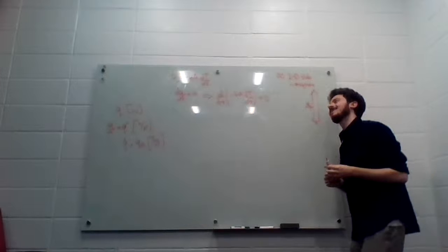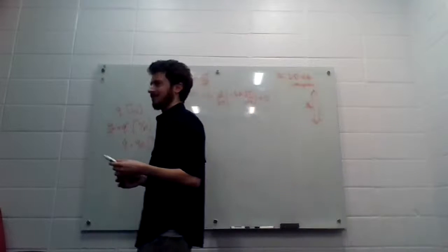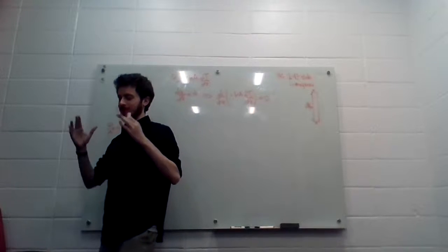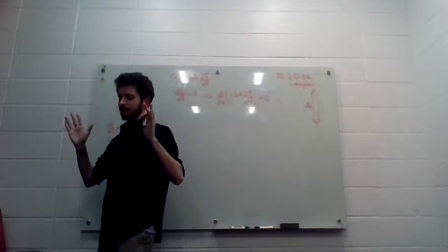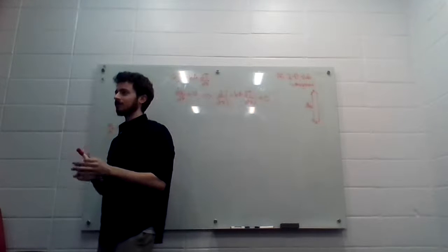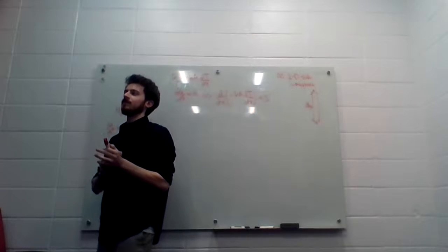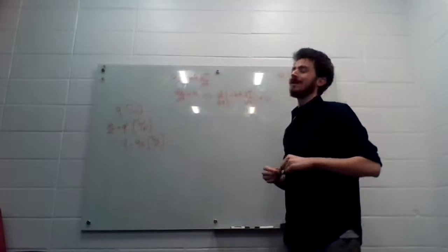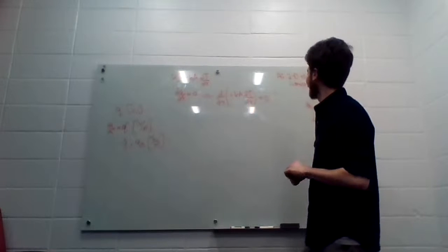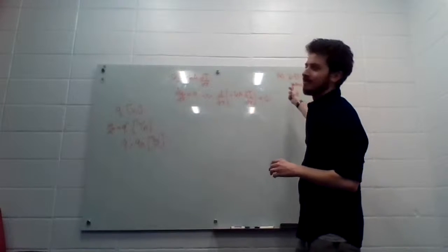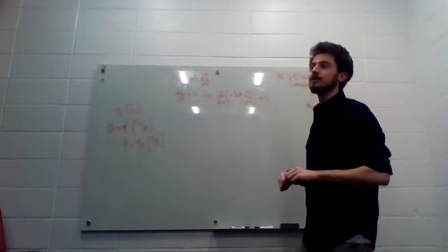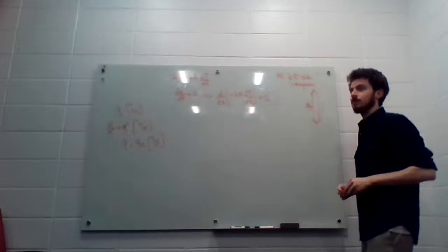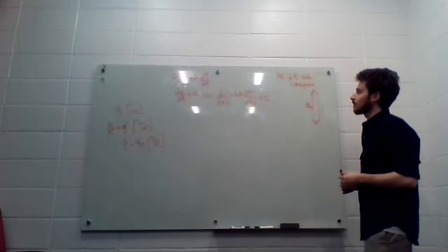Oh, that's very good. Wow. You don't really assume it's an infinite wall. So the infinite wall is the kind of physical abstraction that you need for heat transfer to be one-dimensional. If the wall isn't infinite, it's hard to have truly one-dimensional heat transfer because of those corner effects. But that's a really, really good point. So maybe instead of saying infinite wall, it's better just to say one-dimensional heat transfer through a slab, which tells you the shape of things.